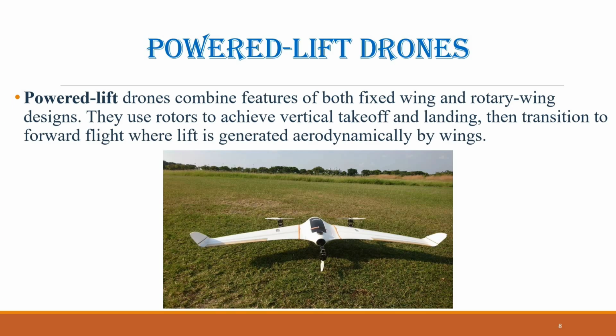Another type uses separate sets of rotors for vertical and horizontal flight. In this case, one set is dedicated to takeoff and landing, while the other is used for forward propulsion. Despite their advantages, powered lift drones are complex to design and operate. Ensuring stability during the transition between flight modes is particularly challenging, which is why these drones are less common. However, when successfully implemented, they offer exceptional versatility.